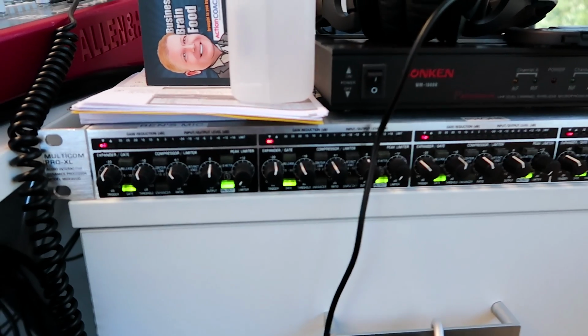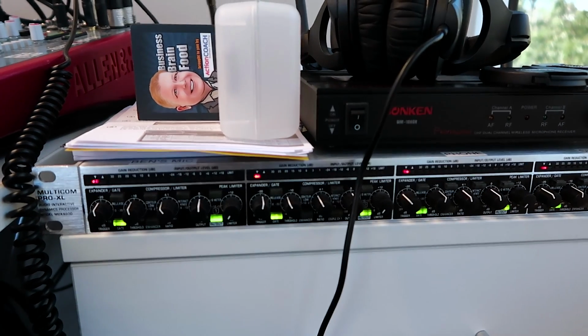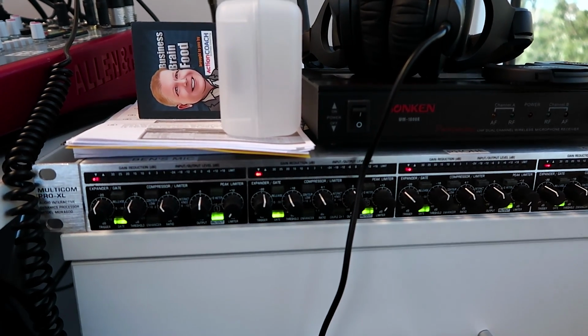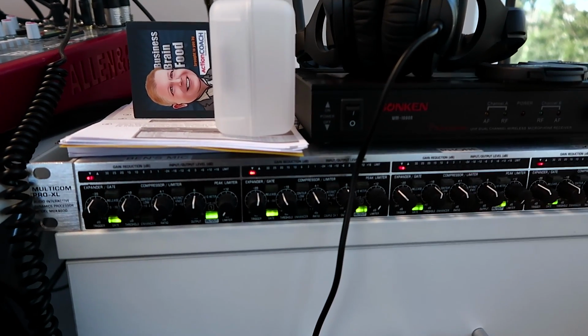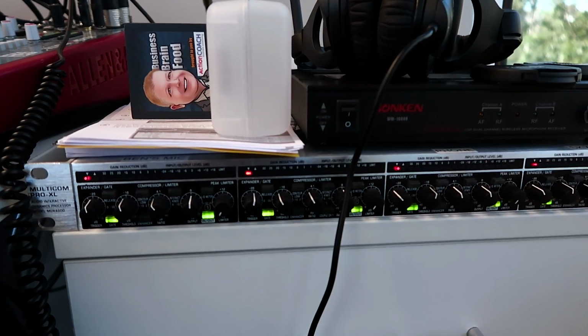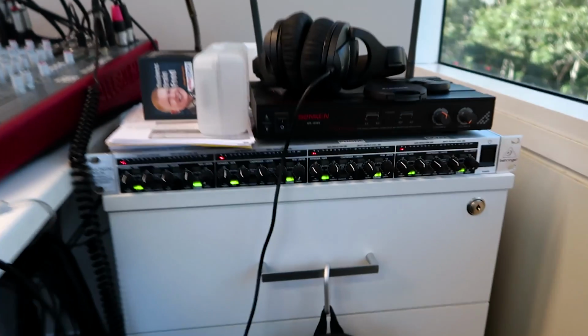The other thing it does is it has a noise gate on it. So if you're not talking, let's say I have you on the phone and it's a staticky line, if you're not talking, it'll actually close the gate and not let any noise through at all. When you go over a certain decibel or a certain volume, it'll open the gate up, and that way I can hear you talking. But at least that way, when you're not talking, the hiss is not there, and that is on all my main devices.